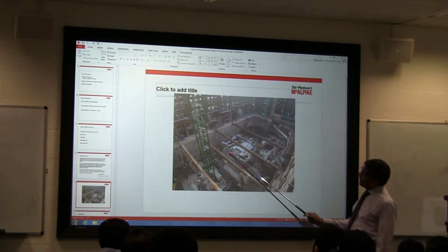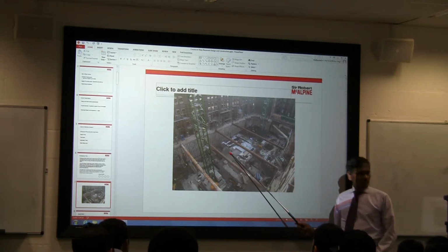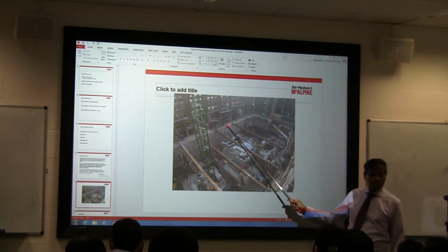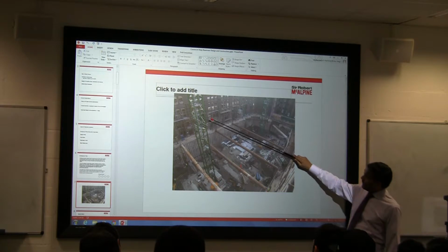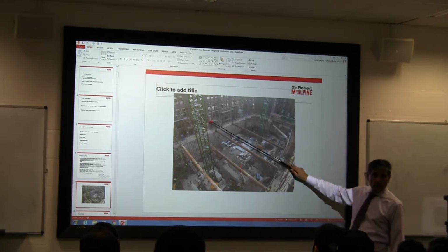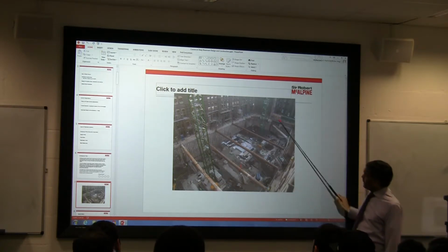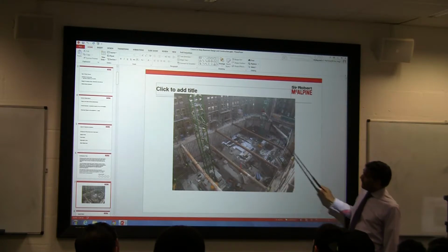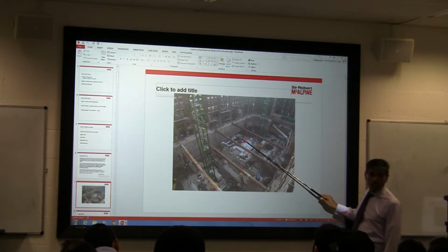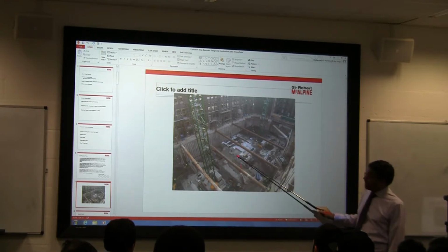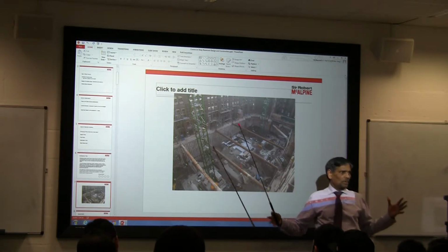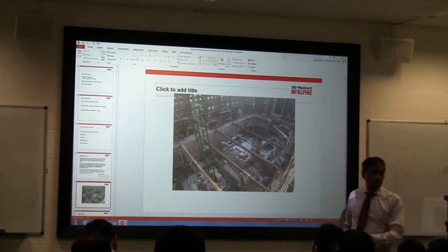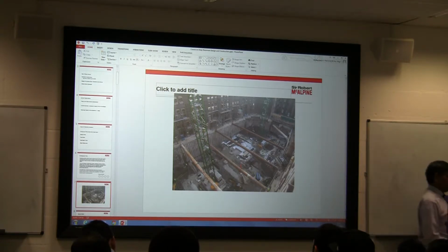And then that is what we are digging, about 13 meters here from the ground level. So this is a series of piles. We start at that level, operate the pile rig to do all the piling, construct the capping beam and start digging down and then build from bottom up. You can see clearly we created the whole big hole in the ground and started building from bottom up. So that's one of the things that we have done.